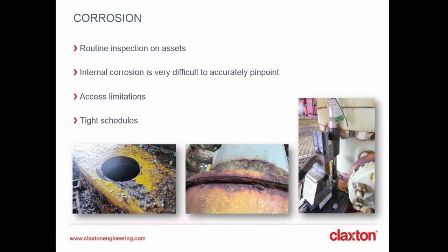As you might imagine, the offshore environment is particularly harsh on equipment in terms of corrosion. This alone merits the regular inspection of equipment to make sure coatings and cathodic protection are working as required. Although in some cases corrosion will be quite visible, in other cases, when the problem is starting from the inside, it can be more difficult to identify.